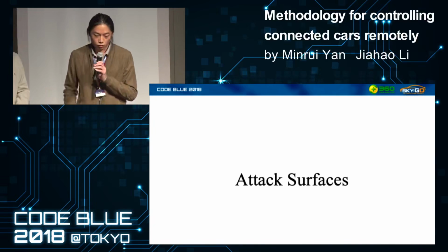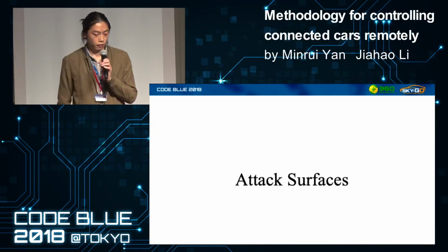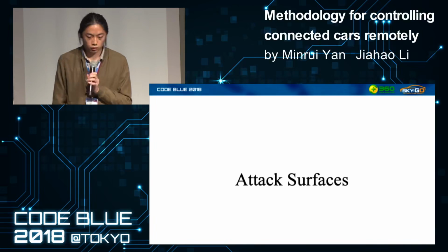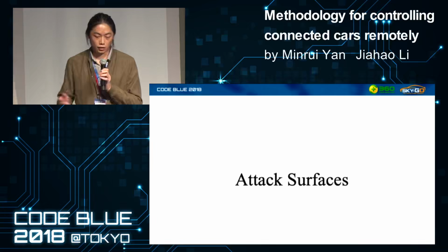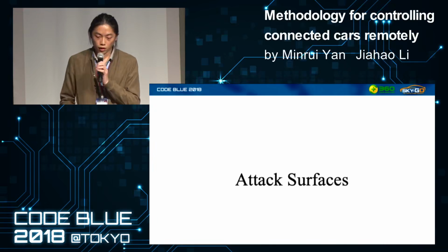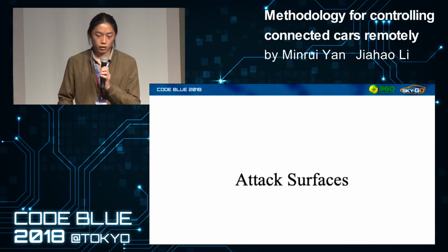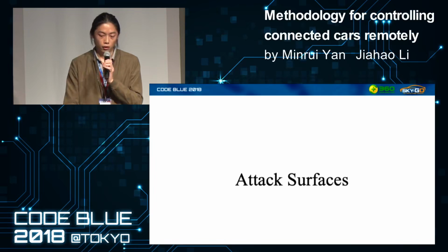All right. To find the attack surfaces for a connected car, you should collect the PCB component information, including the processor, flash IC, and interfaces. Then you can analyze the architecture so that you are able to know which IC is which. And finally, we can analyze vulnerabilities from the dumped firmware. We mainly focus on the T-box, the RVI, and the TSP. I drew several diagrams of their architecture.